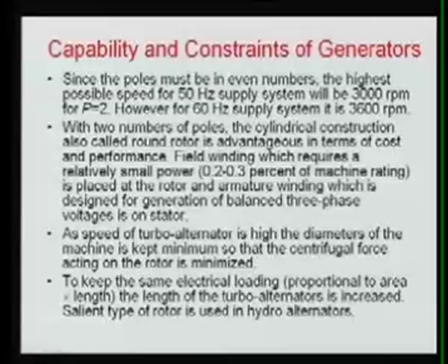as I said, thermal or steam turbines are more efficient. So they should have higher efficiency, and for higher efficiency we have to go for higher speed. If it is a higher speed, then we have to construct our alternator in such a way that it does not feel high centrifugal force. Otherwise there will be the possibility that the poles on the rotor may go out, and that may damage your alternator.